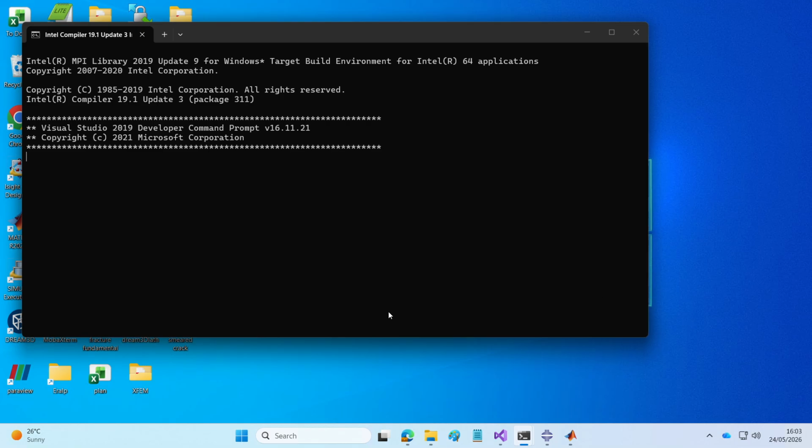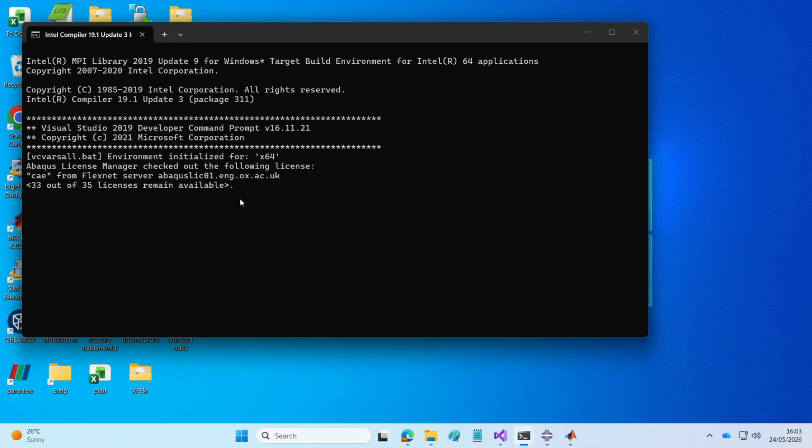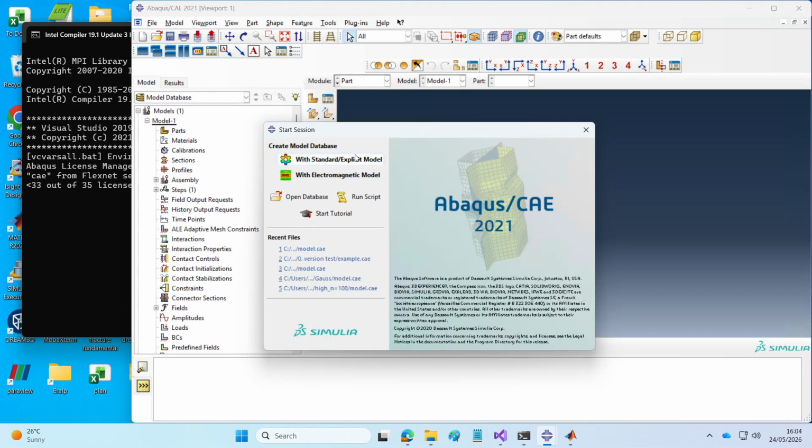So I'm going to create the file from scratch, but you could use Dream3D or Neper and run the cohesive functionality to add the cohesive elements at the grain boundary interfaces. So that's the whole purpose of this work. It could also be a phase boundary, or any other kind of boundary where you want to put these cohesive elements. You just have to define the correct way of naming the sections and material numbers. I'll show you in a moment.